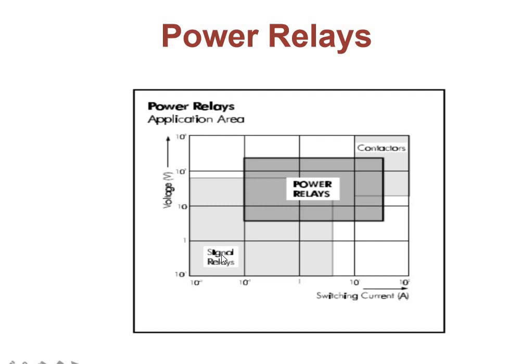So, let us discuss these signal relays. Signal switching relays cover signal, data, and voice switching applications up to approximately 2 ampere resistive load. Typical applications are measurement systems, computer interfaces, and telecommunications. Designs for signal relays include standard yoke type relays, reed relays, and solid state relays.